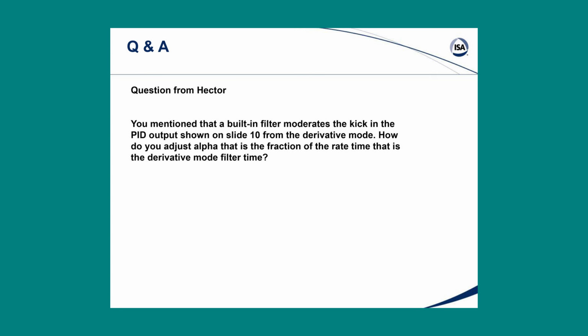The benefit, hopefully what you ought to do is get a better valve. I don't think it helps you get the set point that much faster. I think it's more the benefit you get from the PID gain being larger, that being a sustained step change that gets you to set point faster.